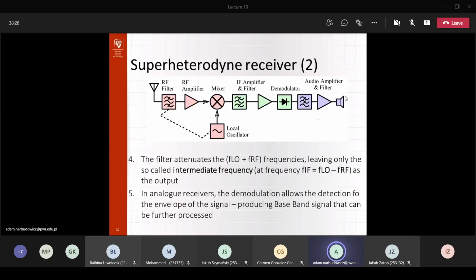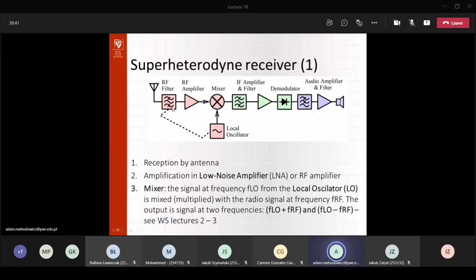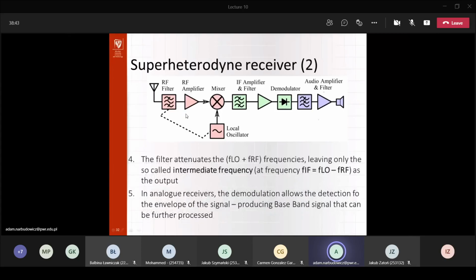Okay. So one thing I should mention here is that, as you see, the demodulation for the superheterodyne is basically performed in two steps, and they dictate the output frequency, and they're all encoded here in color, right? So the red block is the so-called radio frequency signal, in the range of, depending on your system, gigahertz, or 900 megahertz for mobile.